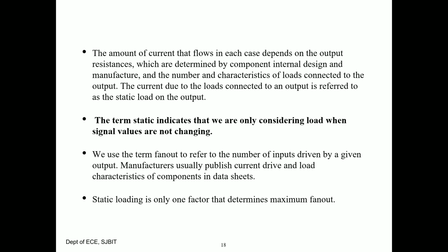The amount of current which flows in each case depends on this output resistance. The term static indicates that we are only considering the load when the signals are not changing. Remember this. The current flow again depends on the fan out, that is how many inputs are connected to the output. All this information will be mentioned by the manufacturer. Static load is the only factor that determines the maximum fan out.